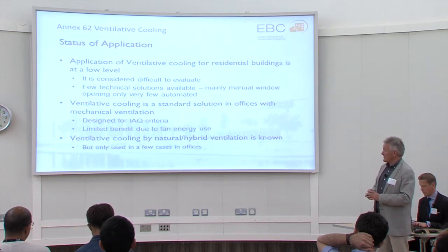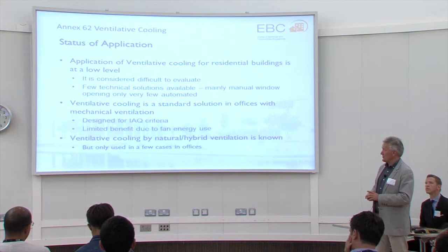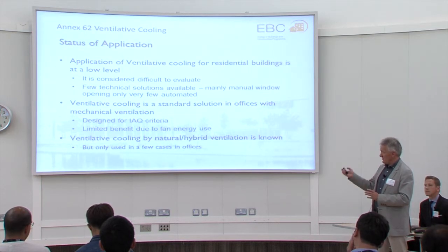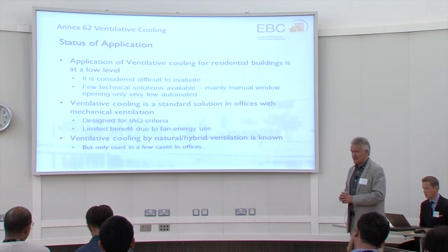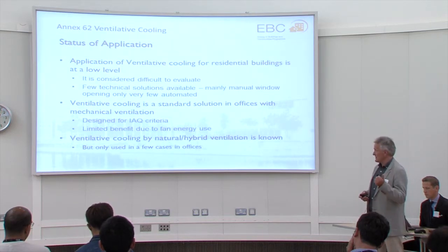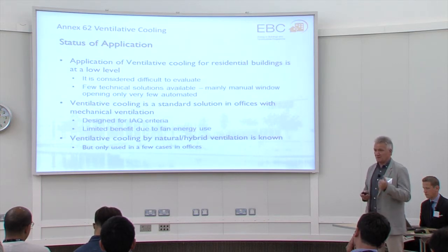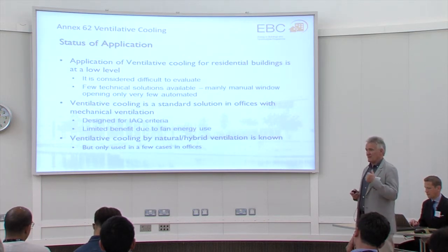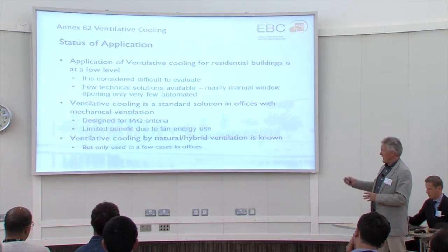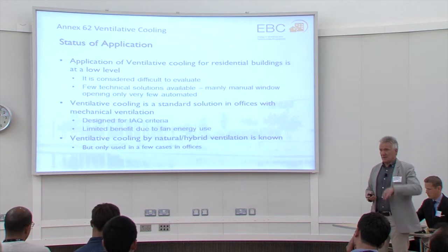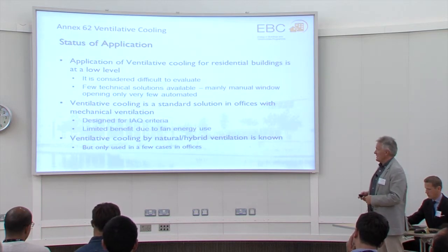While if you look at offices, I think it's a standard solution, especially in offices, to use ventilative cooling, both in mechanical systems, which of course has limited benefit because we have a fan energy use when you use free cooling, and if we require large flow rates to cool the building, the fan energy use increases quite rapidly.